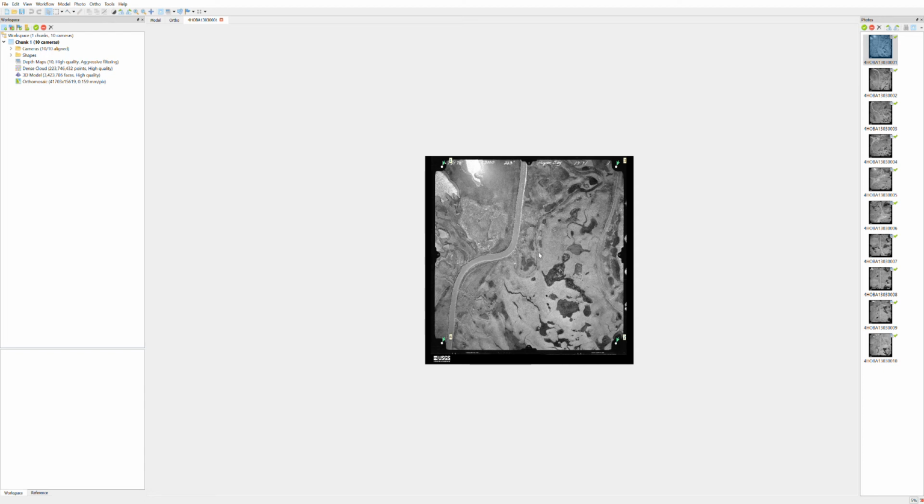So the way that things are measured is using an x and y axis, but x goes from top to bottom and y goes from left to right. And the top is a negative x value and the bottom is a positive x. And the left is a negative y and the right is a positive y. So that means that the number 1, our first fiducial, is placed at the top, so a negative x direction and a negative y direction.